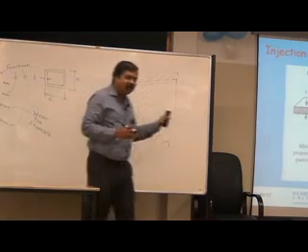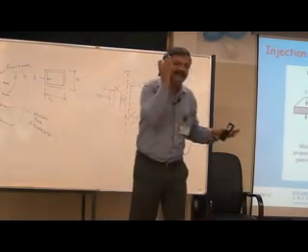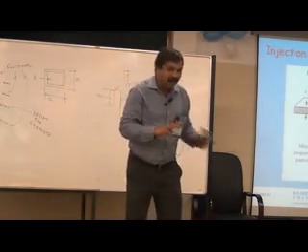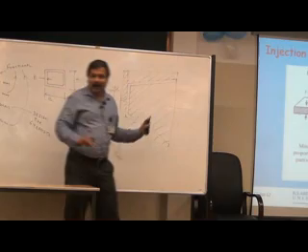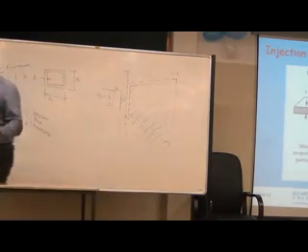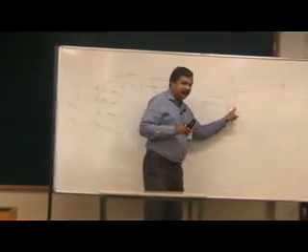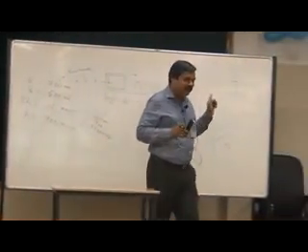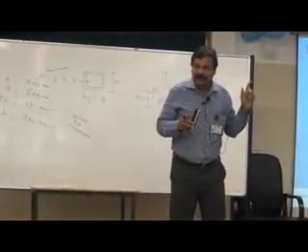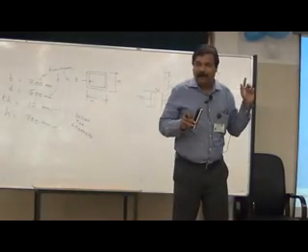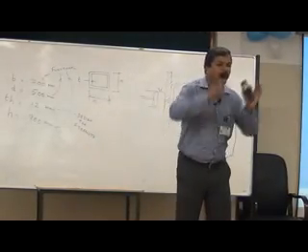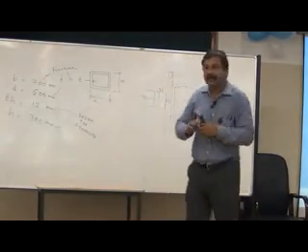There will be a small stem which is protruding outside, that is cut. You can see that mark at the bottom of your bucket. You can take it and tilt it back. You will see a small mark here. That is where the molten polymeric material was entering. All injection molded parts will have this mark.